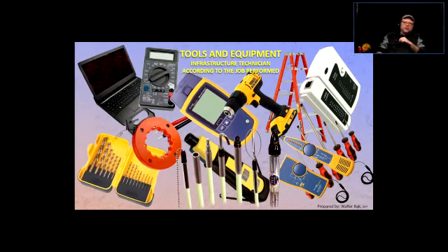Very, very useful. They're also useful when pushing or pulling wires inside walls that have fiberglass insulation or something like that. They're stiff enough. The fish line is just going to change direction and go somewhere that you never know where it's going to come out. That fiberglass rod is nice and straight, so you can push it right to where you want.